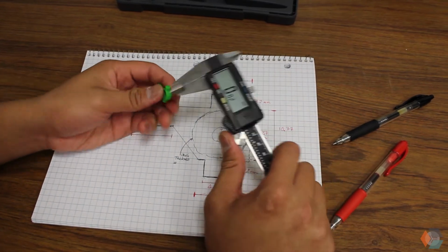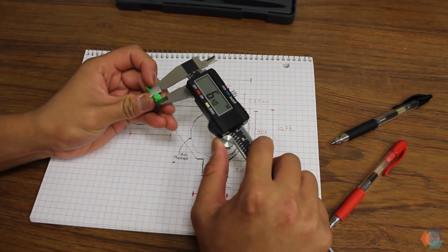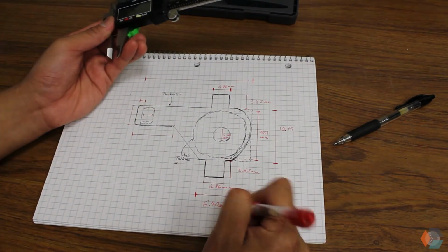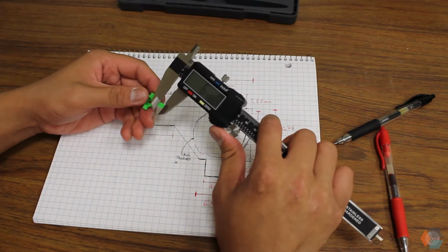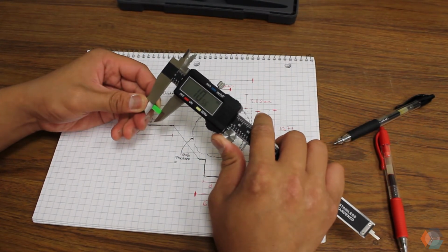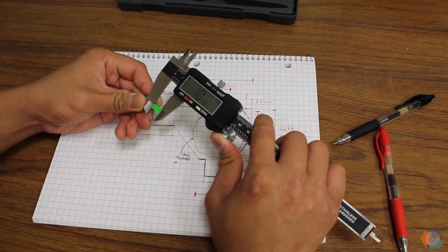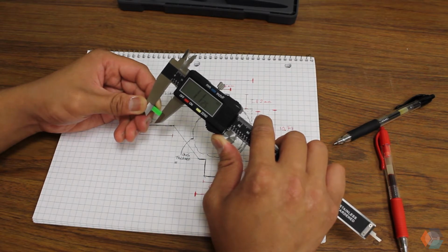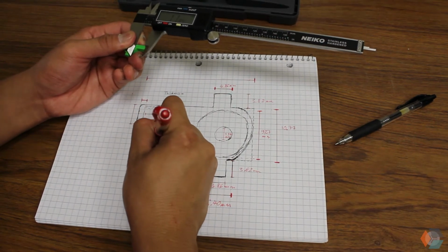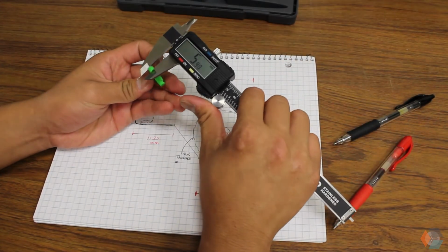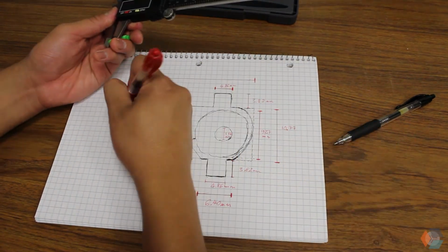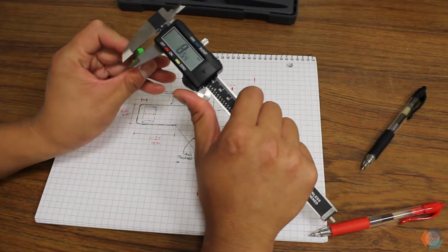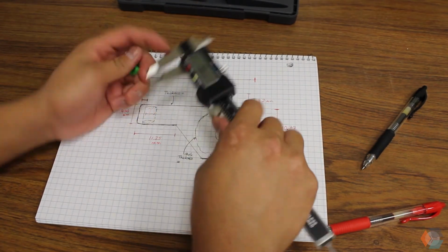Now you flip around, and you can get the overall dimension at the bottom bit of it, which in this case is going to be 6.4 millimeter. Next, we'll go on this end. When you measure, you don't have to be super accurate. You have some room for error. That is understandably okay. So it's going to be 11.25. 11.25 is there. And the height of this guy is going to be 4.4 millimeter. Now let's get the thickness of the piece, which is going to be 5.21.